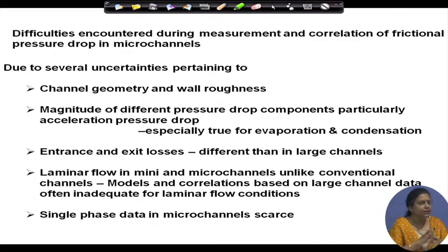And we find that along with that, in microchannels, even for adiabatic flow situations, usually, as I have already mentioned several times, pressure drop is quite significant. When the pressure drop is very significant, then naturally the gas phase, particularly the compressible phase, has a tendency to accelerate as it flows through the conduit.